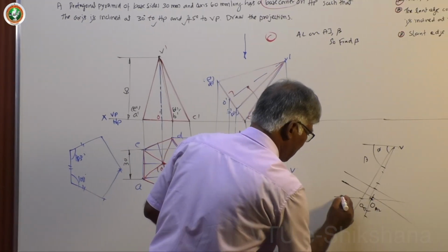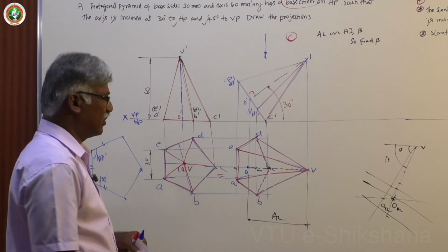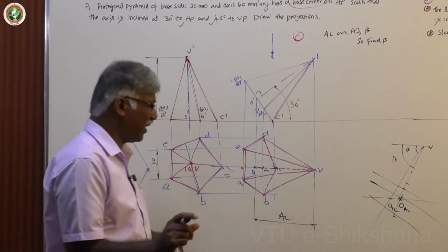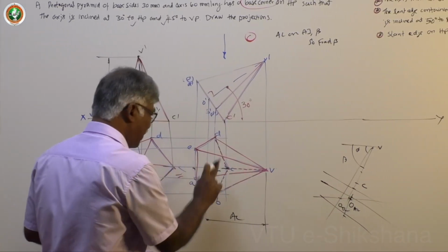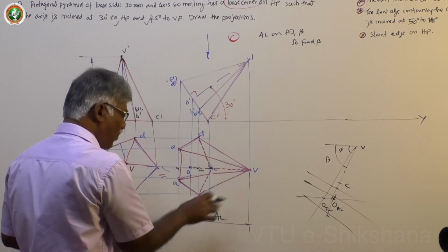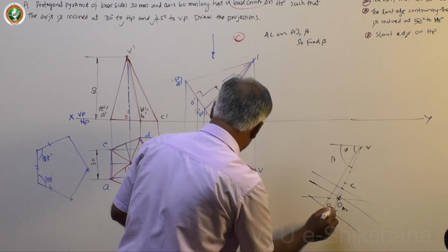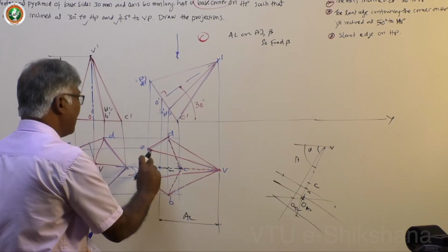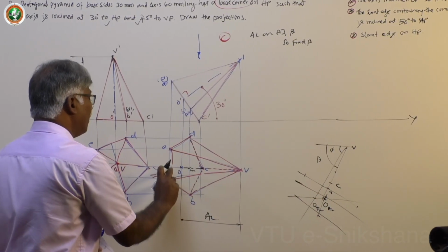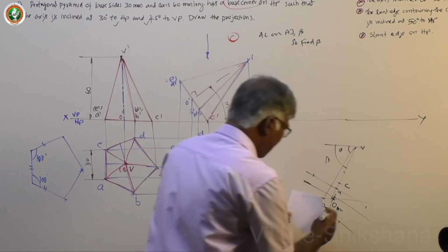Then through that you draw perpendicular lines using a small protractor or set squares. This is C. You are supposed to take only two distances and mark all the points. Let me take MD equal to MB, marked from this O, not from M. So MD, MB, then you take EN equal to NA, that is all. So you will be getting these points.